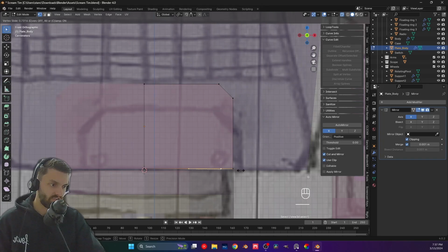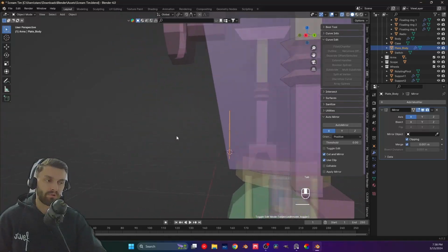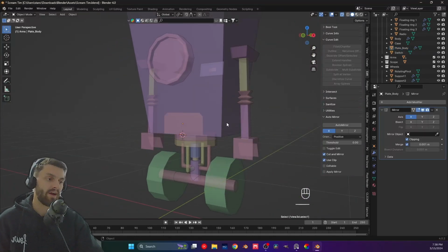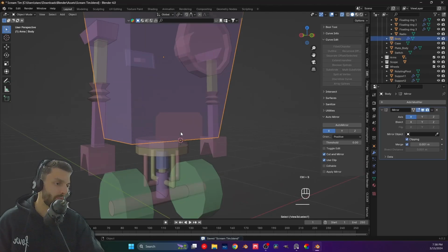Try to get it with GG more or less in the same direction with this vertex up there. And press J. And now because they are connected, what we did is actually create 2 quads, right? Yes, it's a little more geometry, but now at least we have quads again, which is exactly what we want.